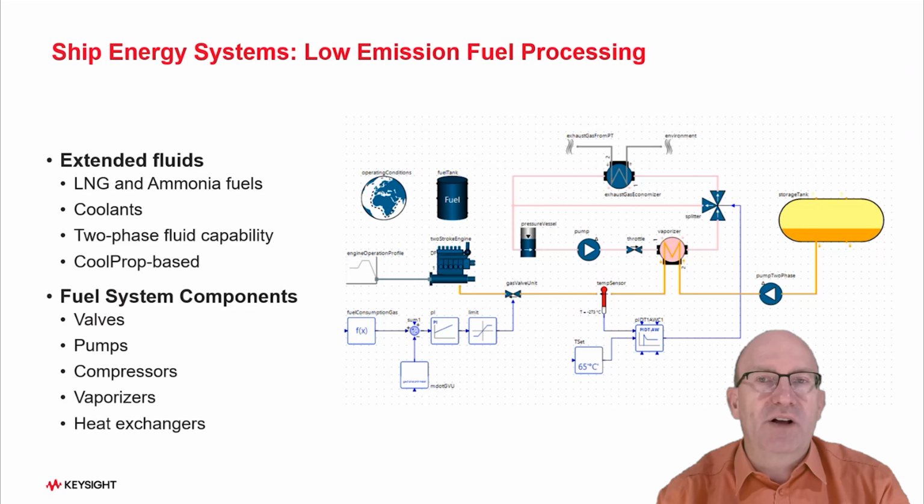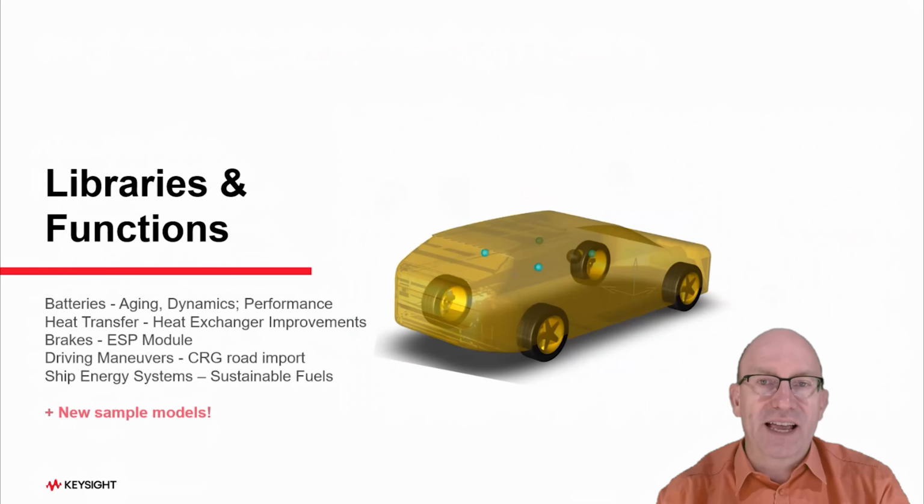In addition to that, of course, the capability of modeling fuel systems requires essential new components so that, as we see here in the circuit, we can model the respective pumps, compressors, vaporizers, etc., heat exchangers. So this is essential if I want to target such systems and make it part of my overall ship energy balance analysis.